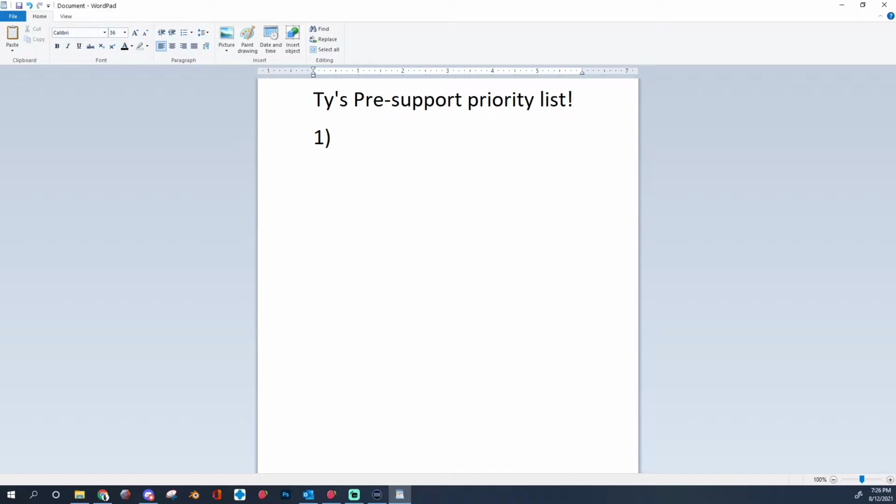All right. Number one, quality of model. What I mean by this is that every time you place a support, you need to have the quality of the model, the detail of the model, first in mind. This is your first question. If I place a support, am I damaging the model? If I place a support, am I going to lose detail? If I don't place a support, what am I going to be missing, right? Every single support, does this adhere to priority 1? This is key.